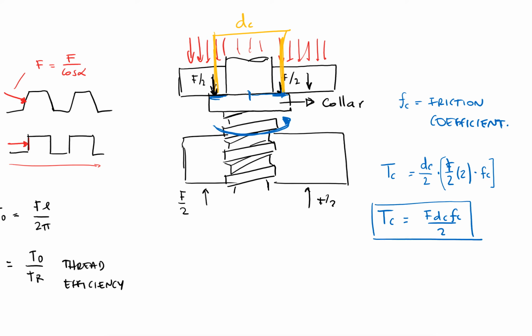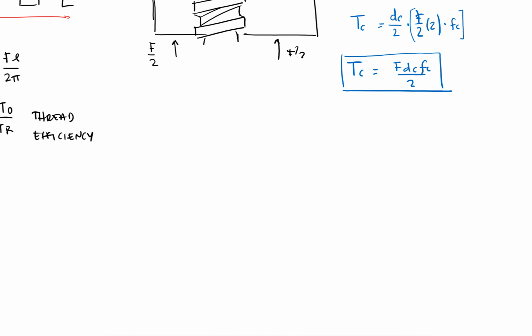Now, so far these are all just forces, or torques in the case of the torques I just mentioned. What we are interested in is the actual stresses, because that's what we use in design. So we're going to use normal stresses, F over A, and we know that this is a compressive stress because it's trying to bring the load up or down, so it's compressing the screw.